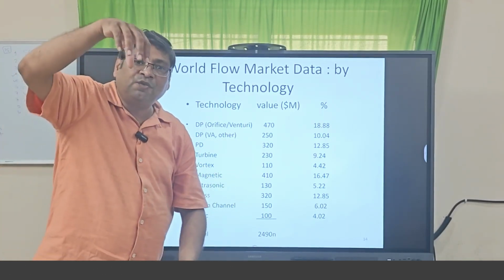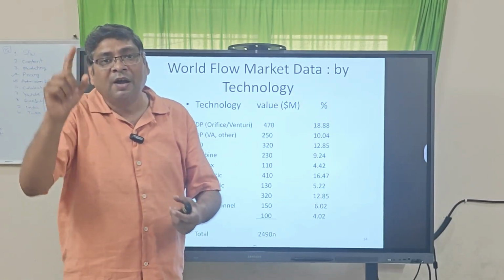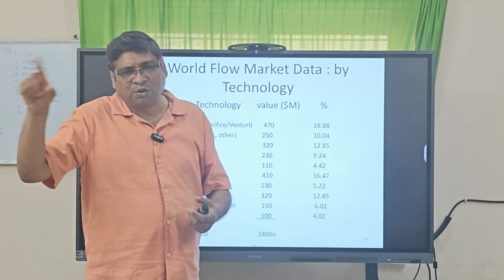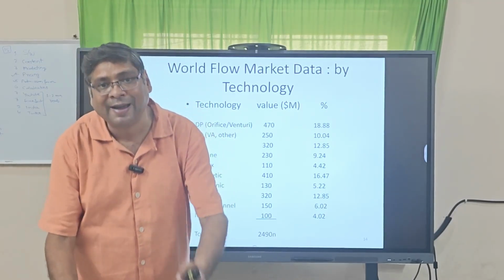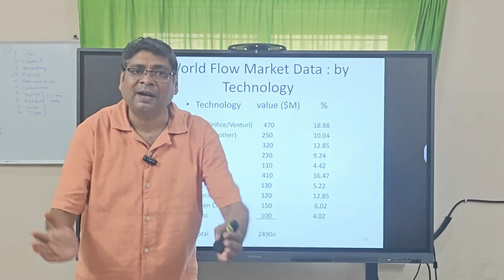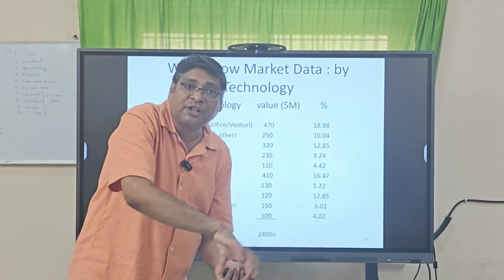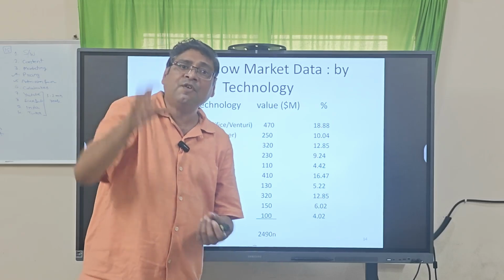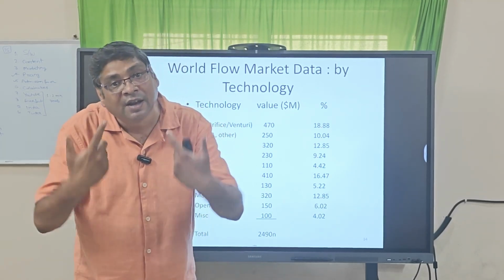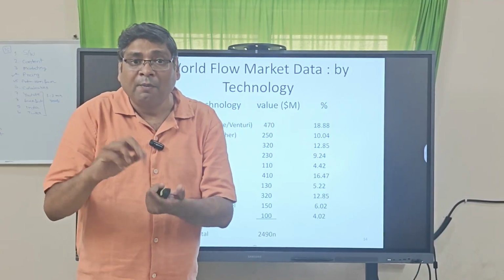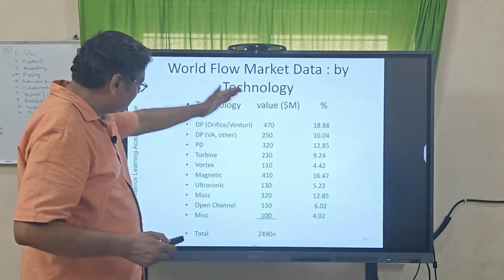We have an ultrasonic level flow meter, and there is an equation with a square root, a 3/2 power kind of equation, of height, and the mechanical structure. In that mechanical structure, we have an ultrasonic level transmitter, and from the civil design we get this equation, put it in the ultrasonic level transmitter, and it will show us the direct flow by the measurement of the level. So this is the value, this is the percentage.